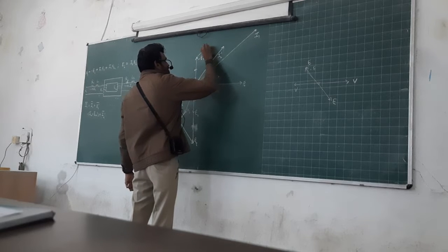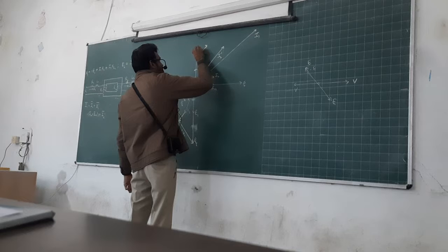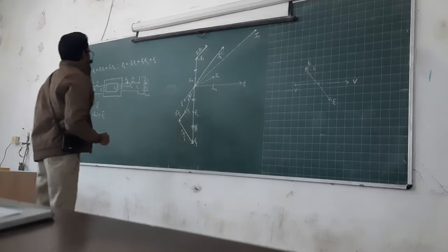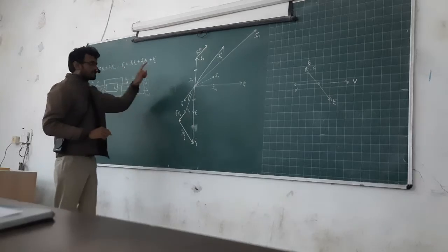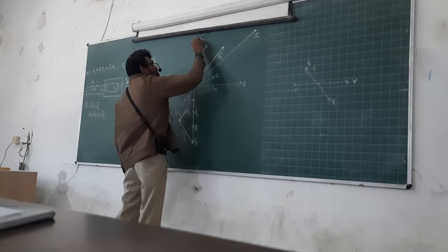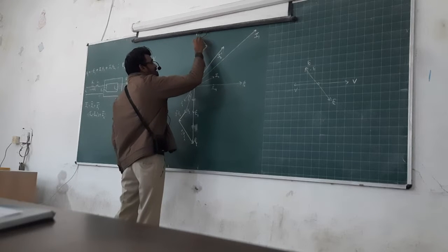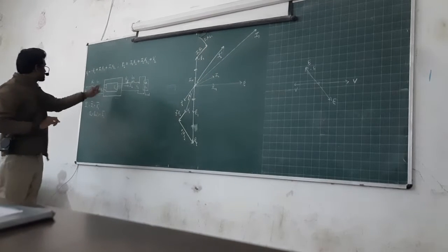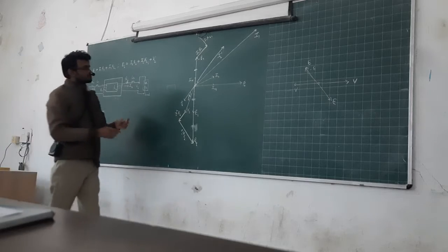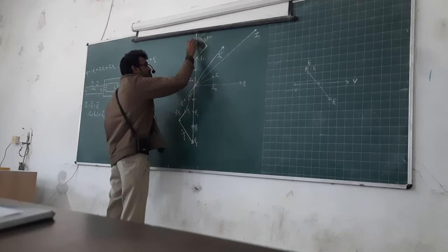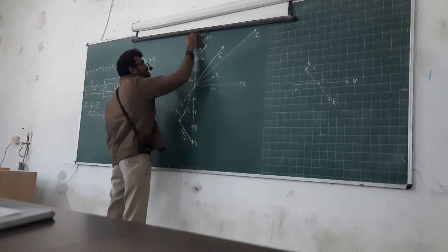Okay, and make a vector which is I1 R1. Then a perpendicular line in this direction. Okay, and then add I1 XL. XL inductor is there, so I have to go 90 degree counterclockwise. This is I1 X1, and then add I1 X1, I1 R1, negative E1. So negative E1, I1 R1, I1 X1, adding all together will give us V1.